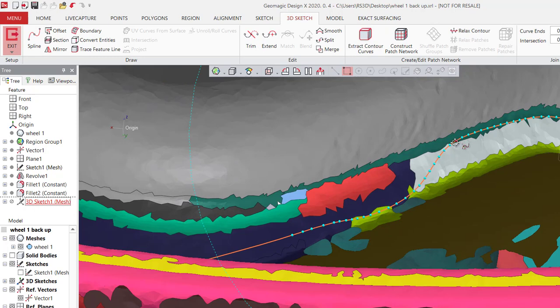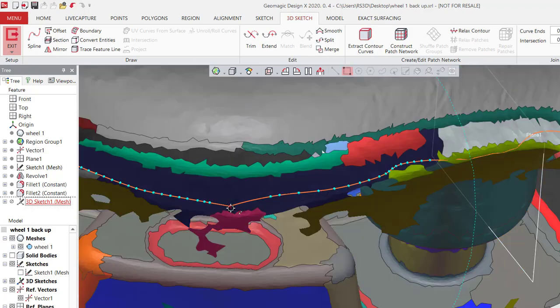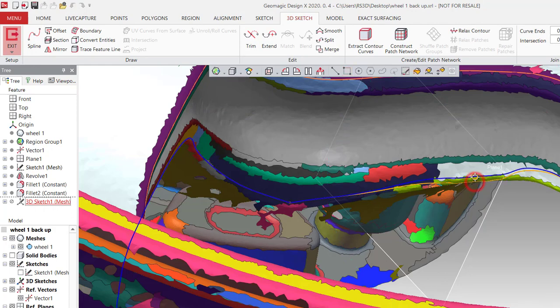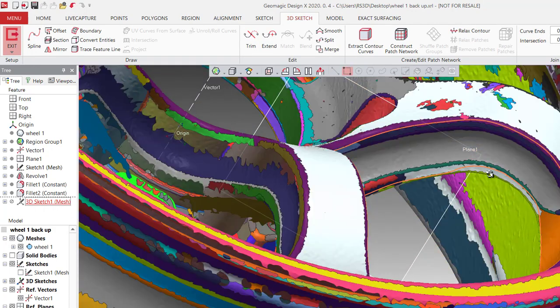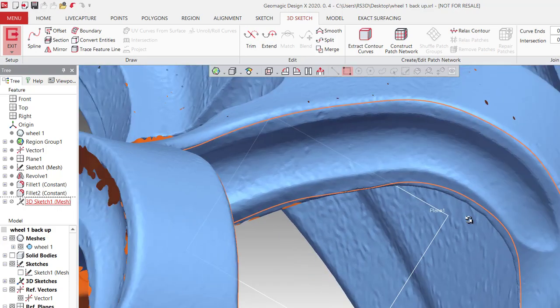As I mentioned earlier, you have to play with the geometry. Pull it down, pull these nodes really smoothly so you don't spill over. Zoom in, pull that down.